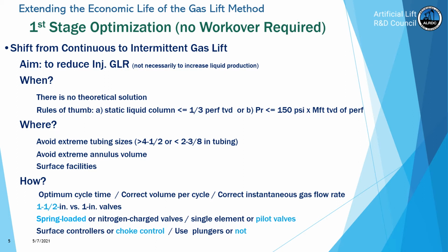But that's not the only problem. The problem is also that it's very hard to predict that closing pressure. So it's going to give you a larger than needed spread, which is very bad, because we will end up over injecting the gas, which is precisely the opposite of what we want to accomplish, but in a way that is hard to predict.